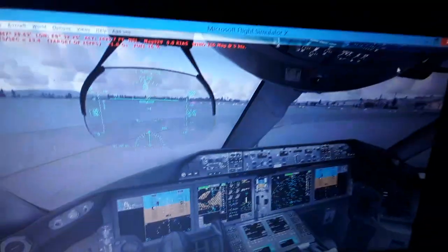We have the flight director crossbars for manual guidance of the aircraft and the autopilot crossbars for automatic guidance of the aircraft. We also have the angle of attack of the aircraft as it flies, and the flight mode annunciator with the autopilot and the autothrottle, and later the vertical navigation modes. We also have the horizontal situation indicator with magnetic heading and track, and the integrated display of the flight plan.